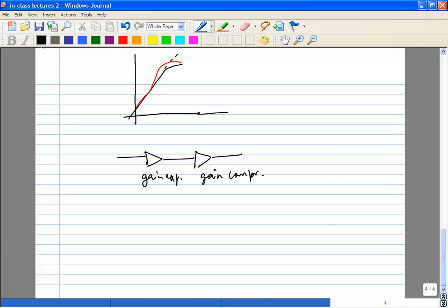You will be using it in such a case when you are trying to cut down something. Of course, if you take a standard off-the-shelf gallium arsenide device, you may not be able to do it. But let's say you want to push the envelope and design the same amplifier in CMOS, where in general it compresses at a much lower power, but you want to compress it at a higher power. Then you would push the envelope and do something like this. When you do that, you will be operating in what was originally the compressive region of the amplifier, and you would see phase and amplitude distortion effects.